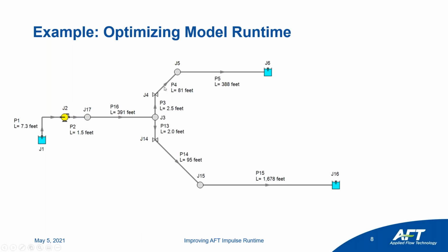We can see that we have some arbitrary division between different pipes. Generally, this might be due to specifying an intermediate elevation. So if this branch is slightly higher than this reservoir, we don't want to draw our pipe going direct from this valve to this reservoir. But by combining these pipes, we can fold that intermediate elevation or any intermediate losses into the pipe as well. That'll help us improve.